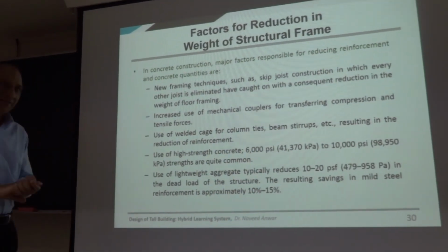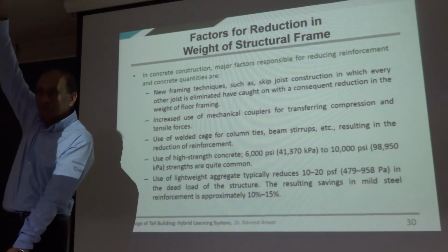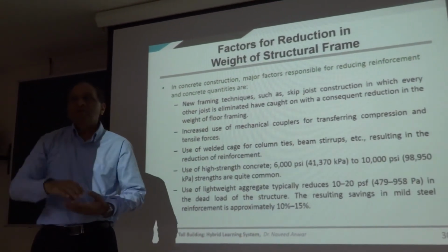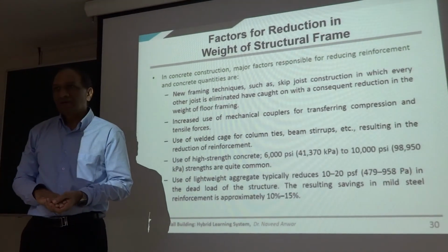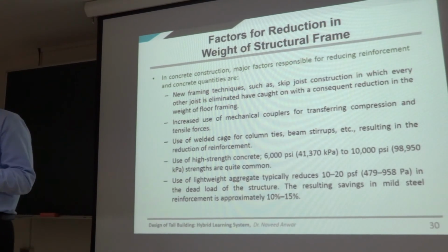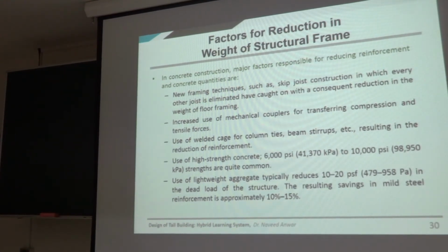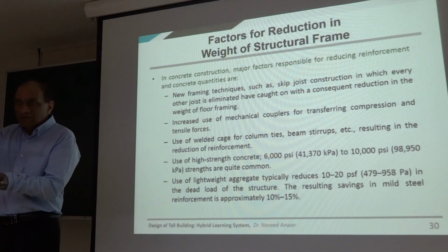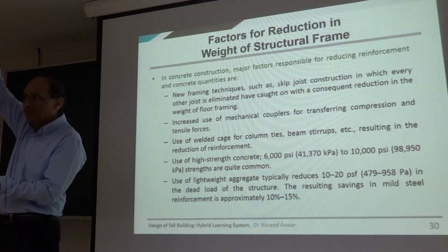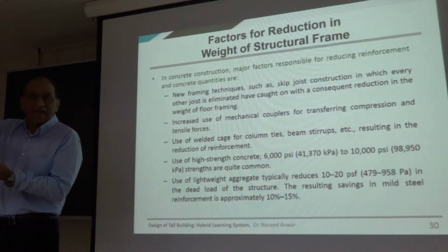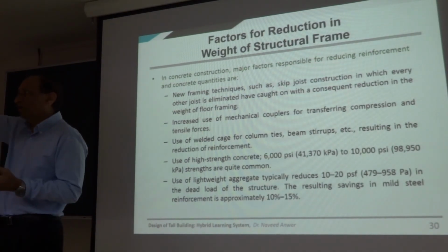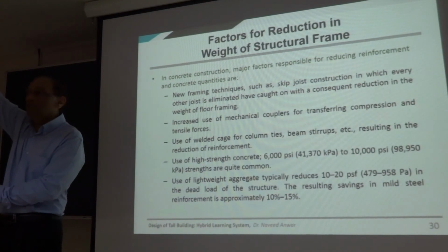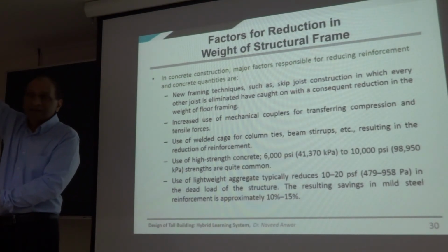And so what people do is, structural floor height is 2 floors, and then they hang 1 floor from the other floors later. Precast or whatever, even the cast-in-place floors, they can come and build later. It makes it easier. Instead of making every floor, you make a floor every 2 floors and leave 1 floor blank, and come and make it in another lighter system and hang it up, so you don't need a joint, or put it on a corbel. So your main structural system is 2 floors high or 3 floors high, and that's what you make.